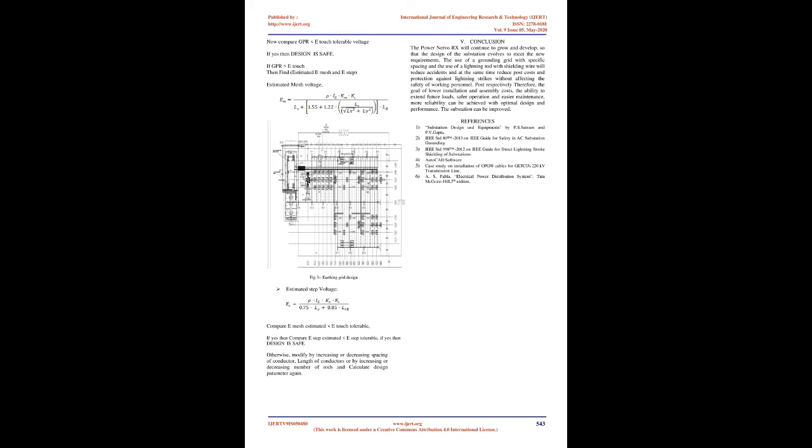If the ground resistivity is 800 ohm or more, it will be difficult to obtain the desired low resistance of 1 to 2 ohm for a network station with a single grounding band. In such cases, it becomes necessary to increase the area of the grounding network. Simply increasing the amount of grounding tape may not help much to reduce the resistance of the grounding system, and the use of deeply driven rods may be unavoidable.